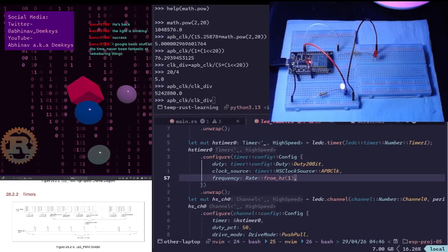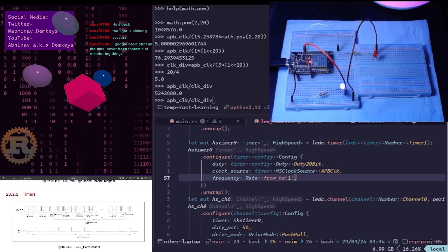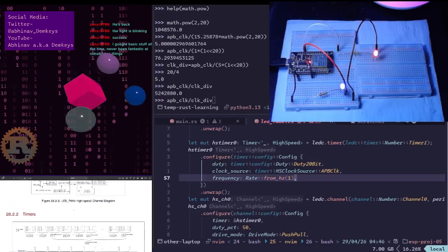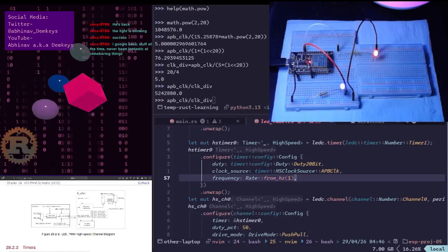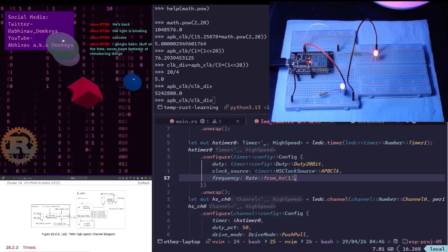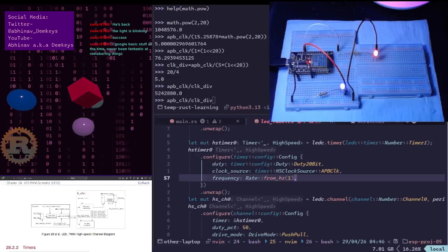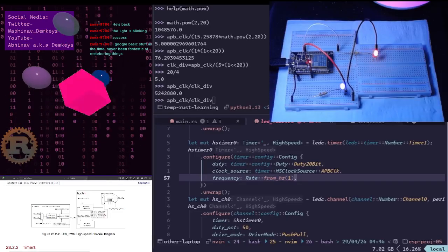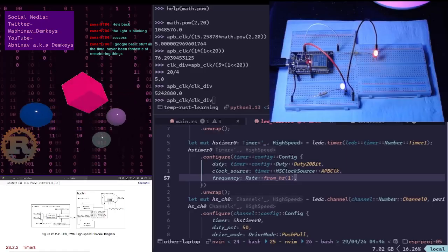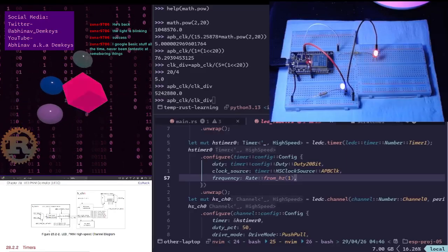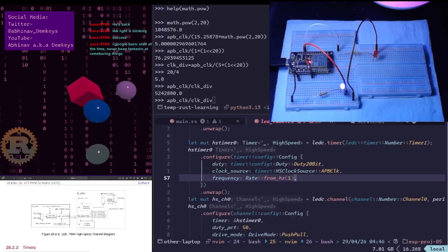Though, if so, okay, if we look at this diagram, our tick signal comes from here, it goes into the fractional divider. My assumption is that it gets divided here, and within this divider we have circuitry that is only going to let one tick every few ticks get through.